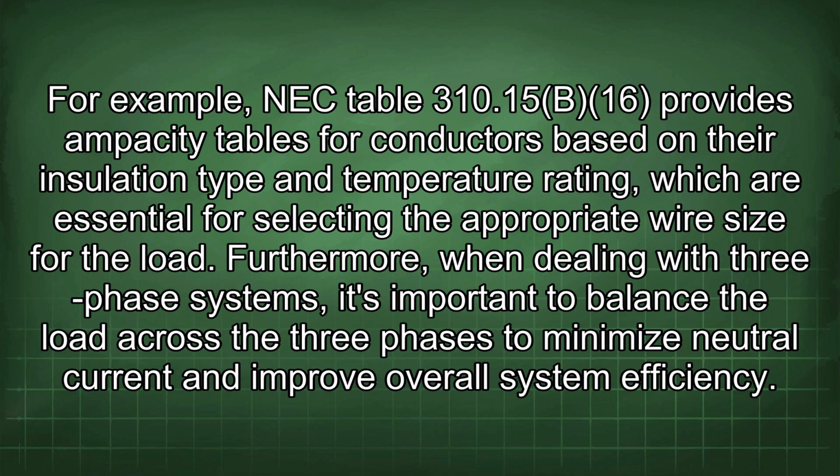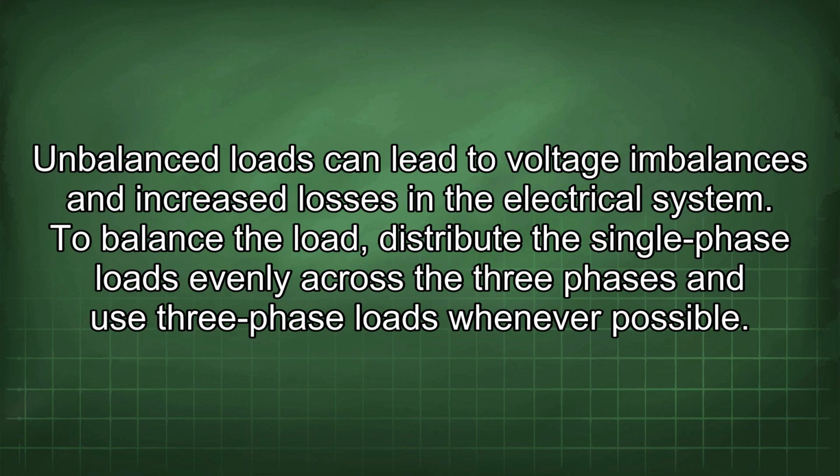Furthermore, when dealing with three-phase systems, it's important to balance the load across the three phases to minimize neutral current and improve overall system efficiency. Unbalanced loads can lead to voltage imbalances and increased losses in the electrical system. To balance the load, distribute the single-phase loads evenly across the three phases and use three-phase loads whenever possible.